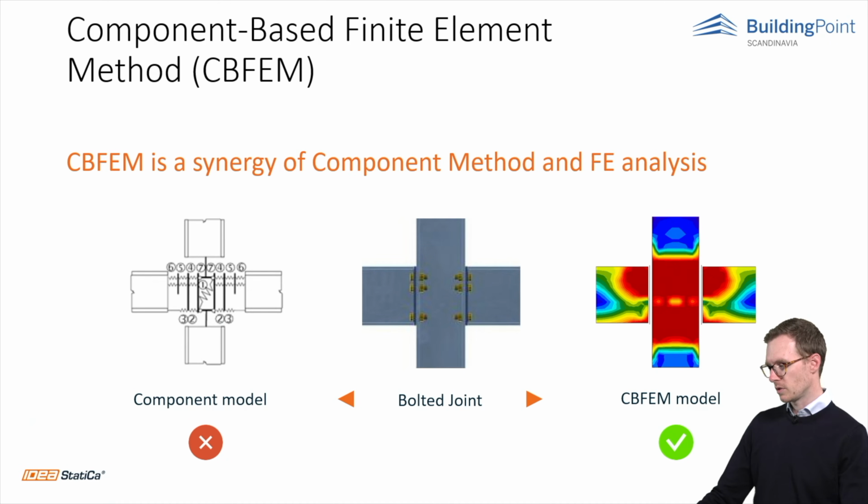The weak point of the component method, generally the analysis of stressed or individual components, was replaced by modeling and analysis using the finite element method. This means it is a unique method for design and code check of steel connections, members, and anchoring. It can be used for the majority of joints, anchorings, and details of various topology.